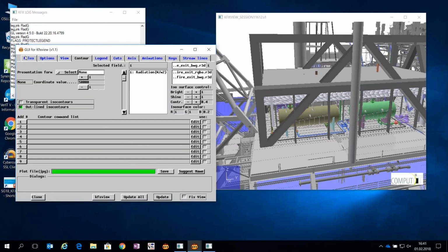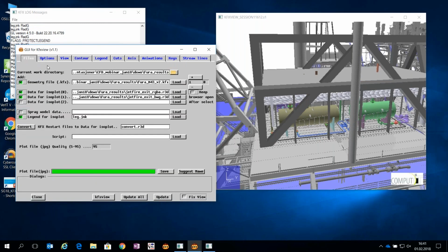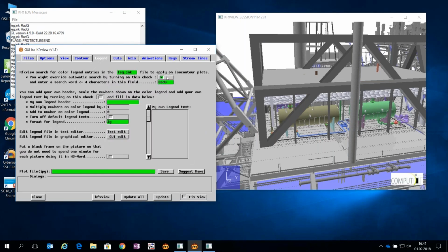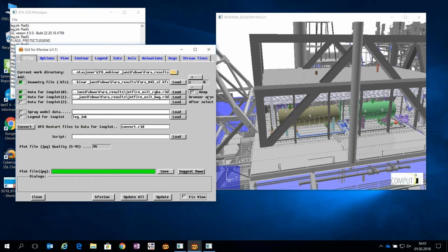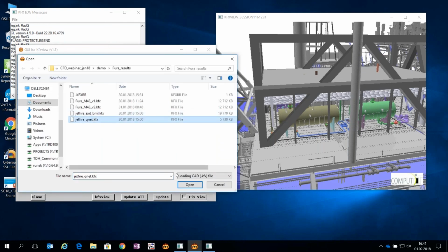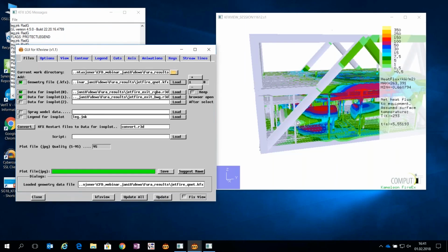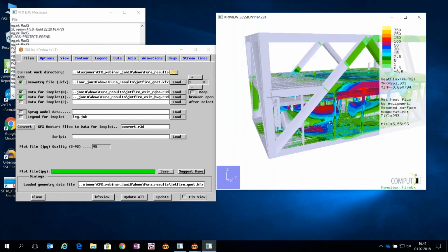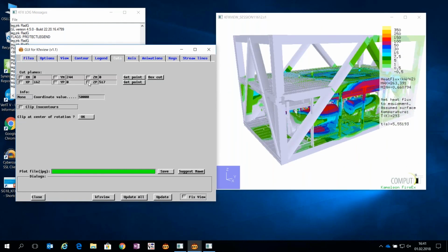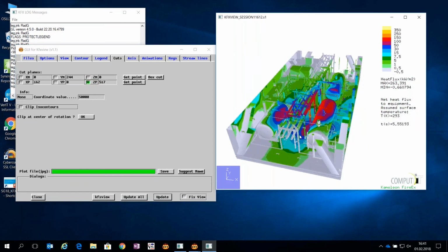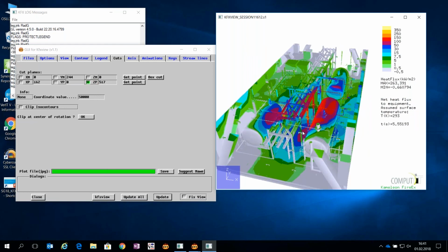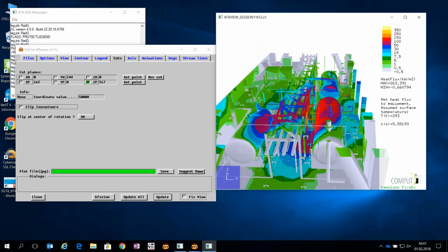So you see again our release point close to this flange, highest heat loads on this vessel, which is impinged by the flame, and now we are showing a combined heat load of thermal radiation from the flame as well as convective heat flux due to hot combustion gases passing the surfaces. While this vessel closer to the release gets less heat loads because it doesn't experience these combustion gases.